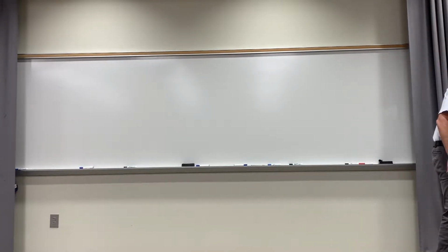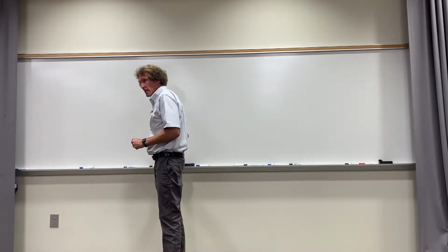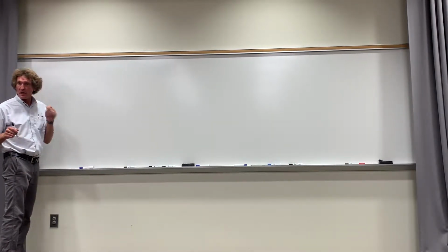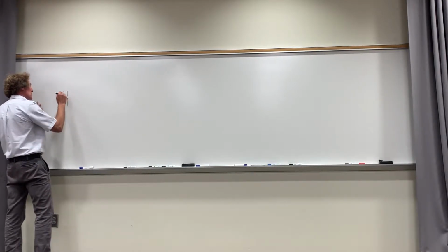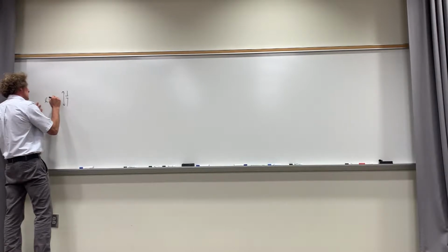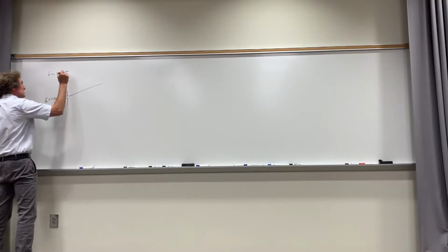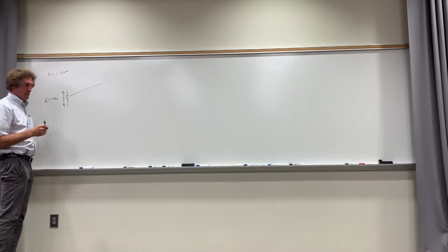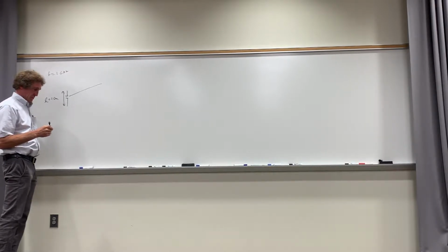Yeah. All right. Any questions about the homework before I start? Yeah, can you do problem 10? Yeah, I think so. Give me the information. It's a 1 centimeter long, 1 millimeter diameter copper wire used as a Hertzian dipole radiator at 1 gigahertz. It wants you to find the radiation resistance and estimate the resistance dissipated by considering the skin effect resistance of the wire. And find the efficiency, and also find the maximum power gain.